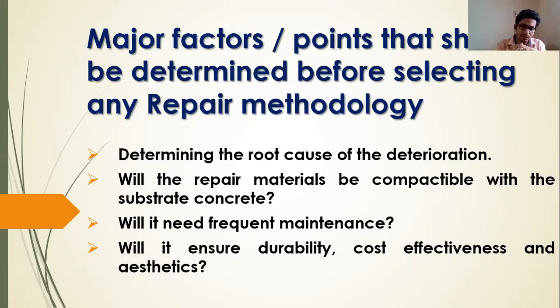Even if you do a very good repair work, the structural element may suffer further cracks or further distress. So you have to see whether it will need frequent maintenance or not. If it needs frequent maintenance, how do we stop it? Because frequent maintenance is not good at all.